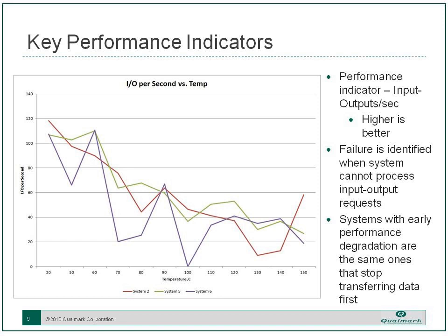In this particular example, if your HASS screen was limited to 70 or 80 degrees, a couple of these products up here, indicated by the blue and red lines, would not have failed. However, they would have indicated degradation in IOs per second, as you'll see in these dips in the blue and red lines, and that can help indicate marginal product and help find products that would fail first in the field.